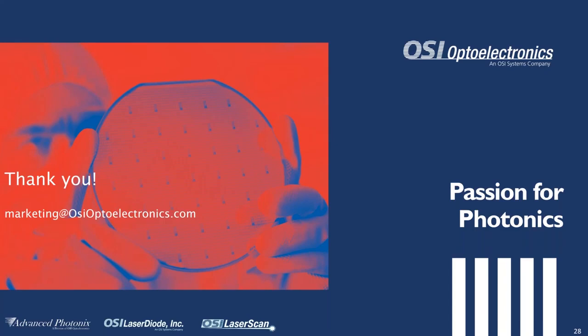So as for any APD, we have to apply some quenching circuits, and the best way to do it is either to use, for example, passive quenching with a quenching resistor connected in series with the photodiode, or, in many cases, when people are measuring light within a large dynamic range, it's very practical to bias the APD in a pulsed mode, when you apply the reverse bias only when you expect the optical quanta to arrive.